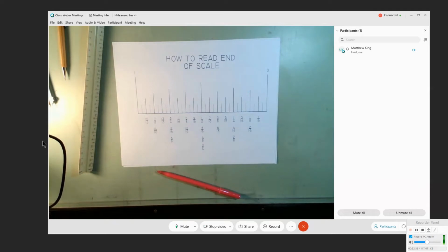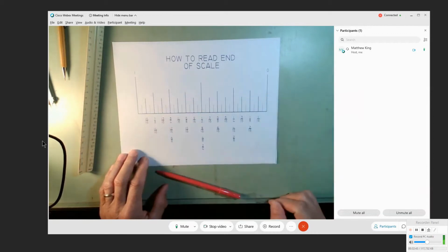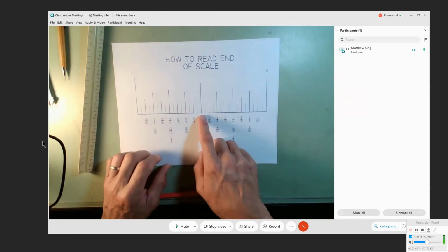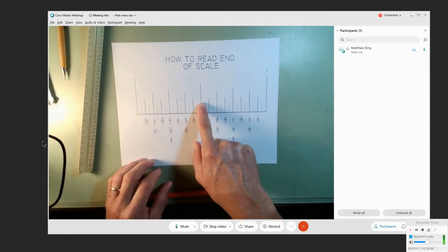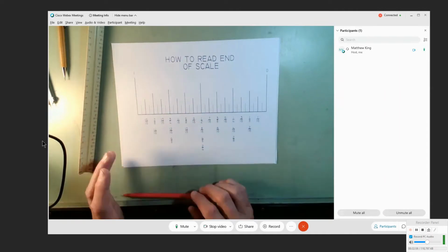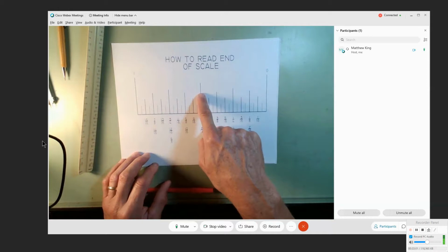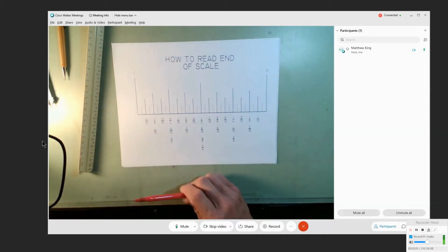Now, if I were to tell you to find the 11/16, sure, you could go here and say 1, 2, 3, 4, on your way up. Or, you're starting to get it when you say, well, I can find 8/16 or a ½ inch really fast and then just go from there, 9, 10, 11, right? So when you start getting to ones that you can find easily to get to the one that you really need, that's when you step up on the experience ladder.